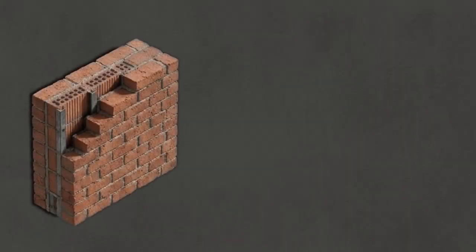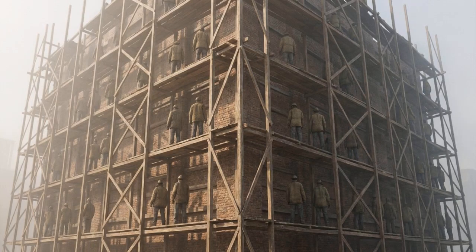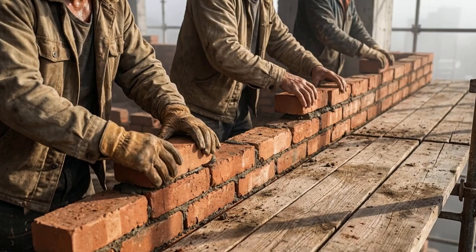When masons and materials load onto the wooden platform, their combined downward weight travels along a precise path. The energy flows through the platform, into the putlogs, and transfers straight into the permanent brickwork. Because of this physical connection, a bricklayer scaffold functions as a temporary extension of the building itself. The framework trades standing on its own for the advantage of climbing rapidly alongside the masonry.